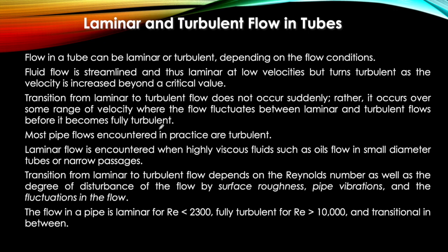So previously under external forced convection, you already know that the flat plate has a critical value, where when you calculate the Reynolds number beyond the critical Reynolds number, it will be considered as turbulent flow. Whereas for a Reynolds number below the critical value, it will be considered as laminar flow. Normally, laminar flow is at low velocity compared to turbulent flow at high velocity.